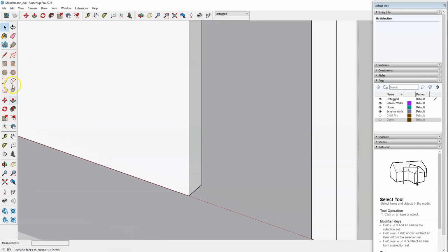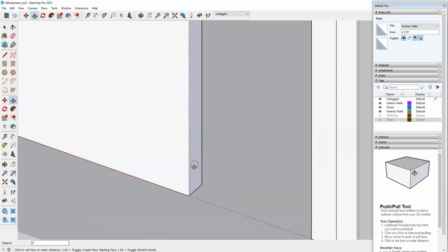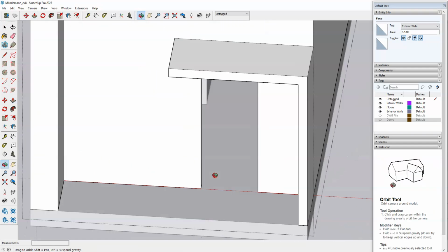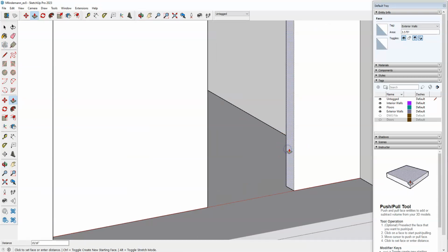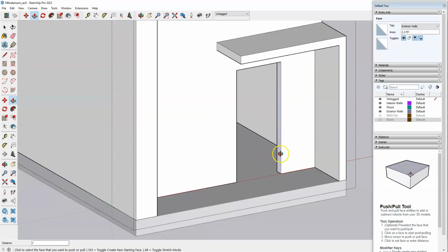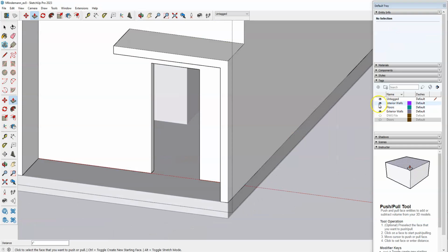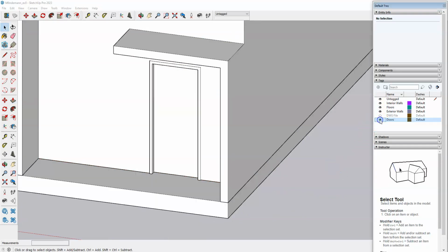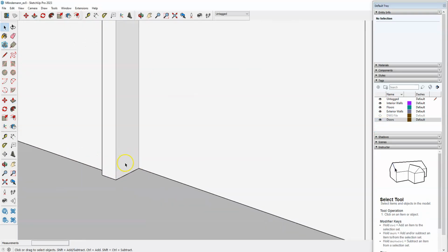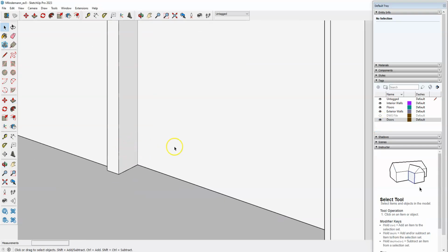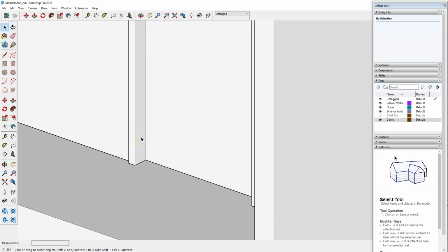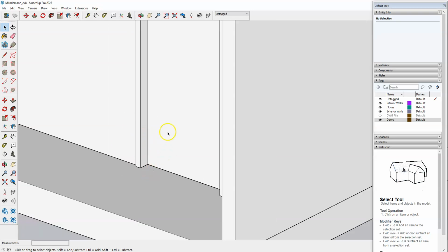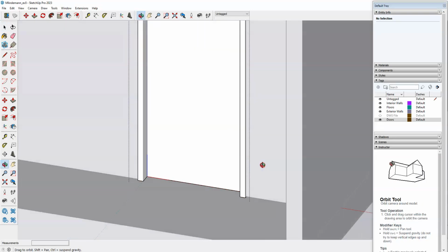You can edit these and push it back just a little bit more if that bothers you. So I'll just push them back an extra inch in each direction. And now if I were to turn my door back on, that gets rid of that line, because we're no longer seeing the exterior walls through our door frame.